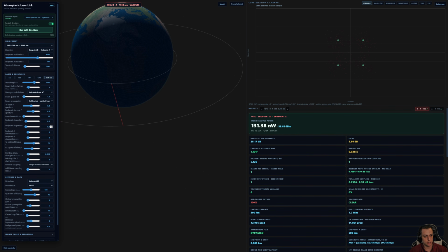Alternatively, you could stick with the coherent 200 gigabit, 400 gigabit links and just use a larger aperture on the satellite in MEO, since it's going to have a higher capacity there, and that will get you to the ballpark of the commercial transceiver and Starlink terminal range, minus 33 dBm. Okay, that should give you a fairly good bit error rate.